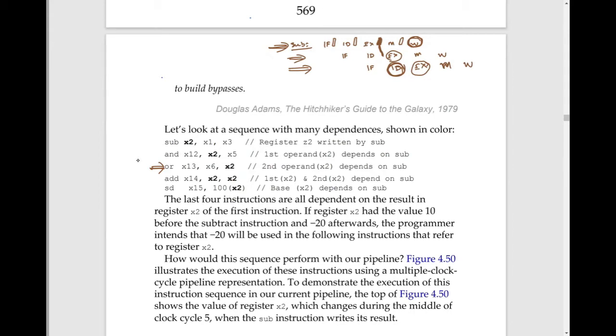So from where can we forward? We need to forward it from this register. How? After execution, concentrate on the first instruction: the result will be stored here. Then in the next phase, normally from a pipeline register, we read all the values from here, perform execution here, and write the data back here. This is the property of the pipeline register that I explained in the last class.